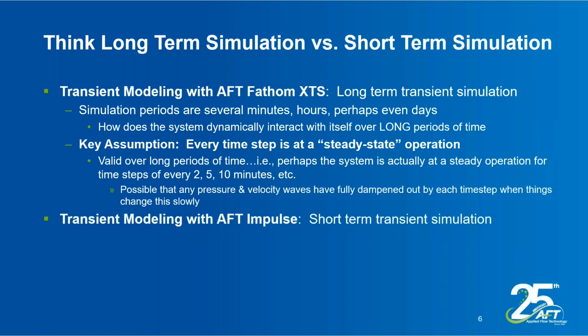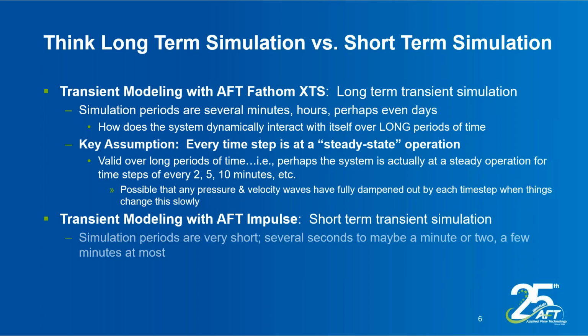Now, when you're dealing with AFT Impulse, it's a different type of transient simulation. You're looking at a very small window in time. XTS looks at very long periods of time. Impulse looks at what's happening essentially instantaneously at a certain moment. So let's say that you have a sudden valve closure or a pump that all of a sudden trips, as an accident type of scenario, perhaps. Then you're looking at a very short window to see what's going to happen within that time frame.